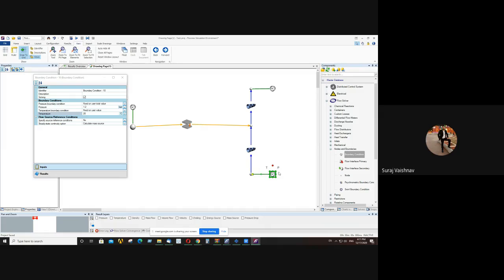Sir, then you can only assign the pressure boundary condition here. So with a pressure difference, you will get a certain amount of flow within this element. I'm not saying you can specify the velocity boundary condition here. Listen, what I am saying is that velocity may be 2 meters per second at 100 kilopascal, and velocity may be 2 meters per second at 1000 kilopascal. So I'm asking whether my student will be able to study the effect of Reynolds number or not.